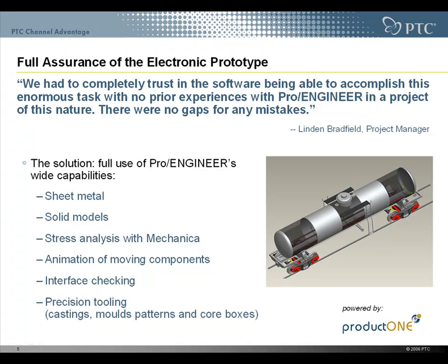They created stress analysis reports with ProEngineer Mechanica. The ultimate tool for selecting materials and design acceptance was used iteratively as part of the design process as each design modification happened. With animation of moving components, by linking components and setting their degrees of freedom, GRE could establish with confidence how parts interrelate under load, wear and braking conditions.